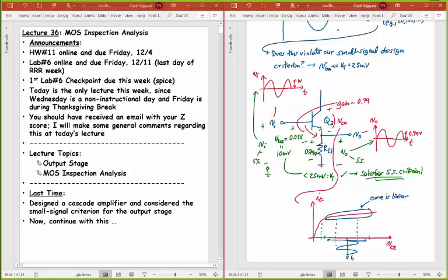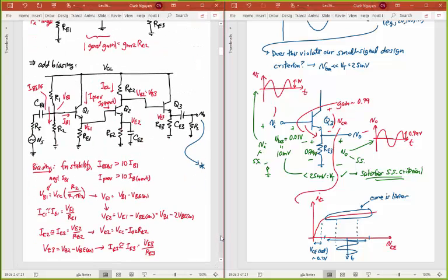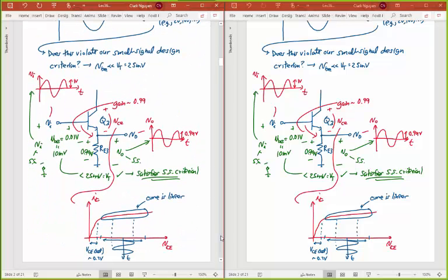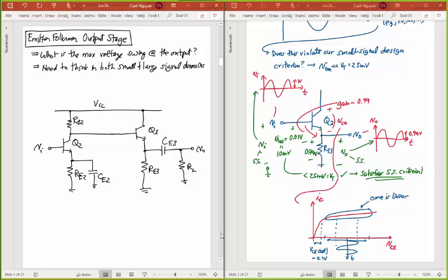And remember, this point is where you start going from forward active into saturation. This voltage here is the VCE saturation voltage, which tells you that in order to keep the signal linear across VCE, you have to make sure that VCE never goes lower than this VCE sat, which is about 0.2 volts. If we start getting lower than this point right here, then we're going to start going nonlinear. Then our small signal analysis no longer really works, and we have to use nonlinear equations for everything.